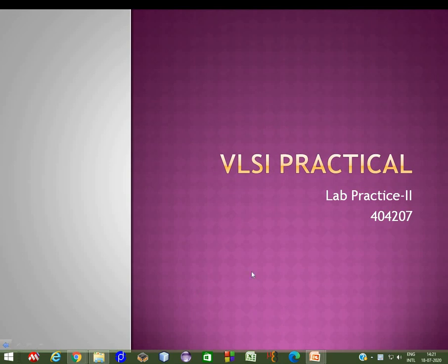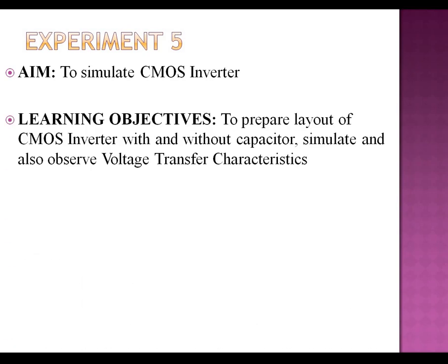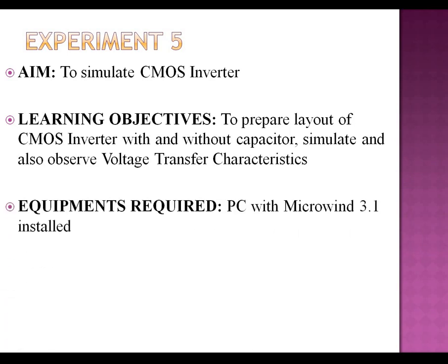Today I will be discussing the VLSI practical. In this part B, that is preparing layouts, the aim of this experiment is to simulate a CMOS inverter. The objective is to prepare the layout of a CMOS inverter with and without capacitor, simulate and observe voltage transfer characteristics.